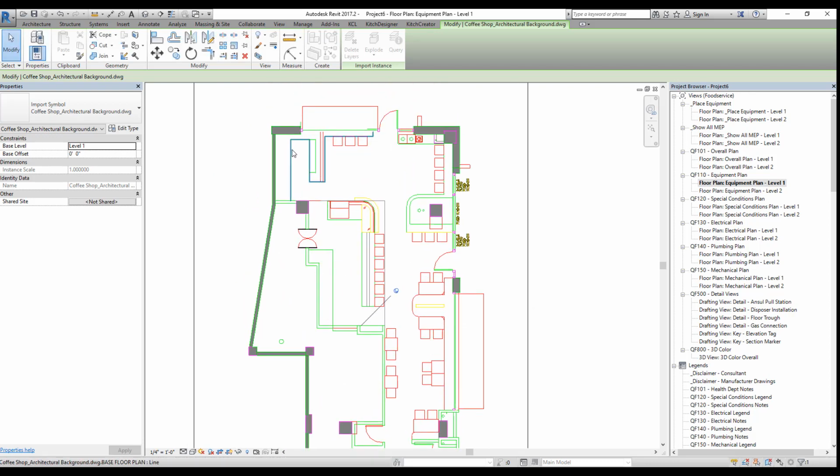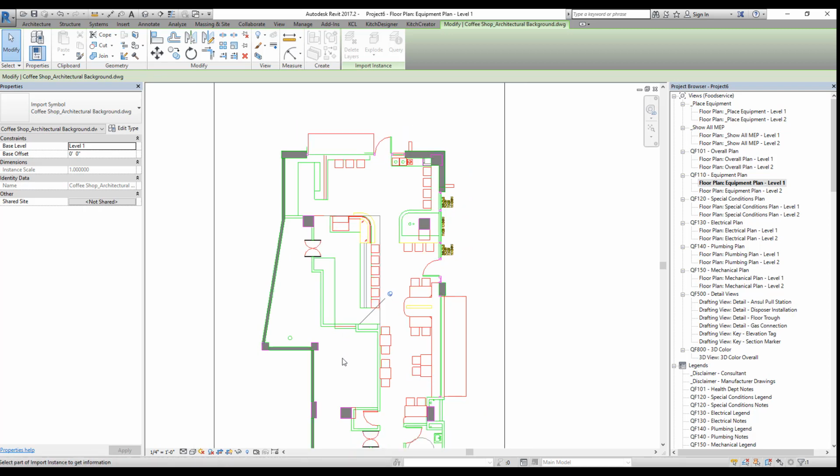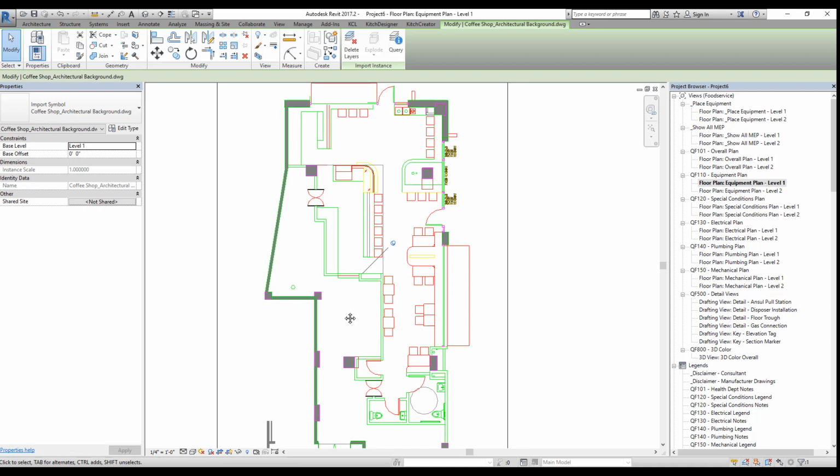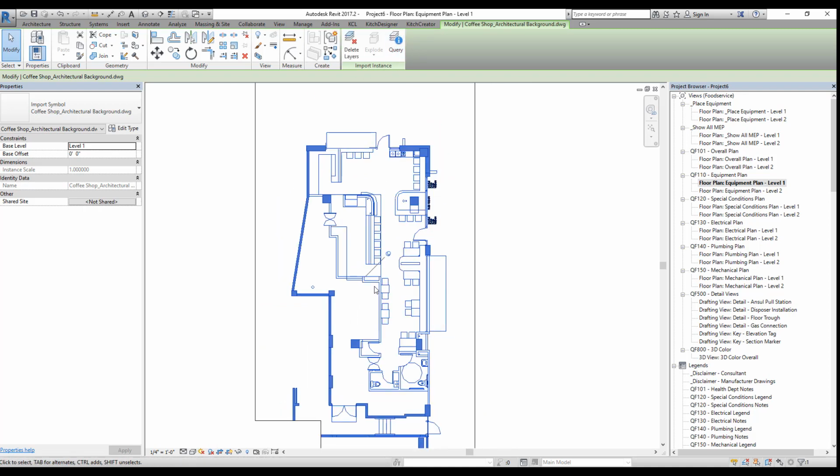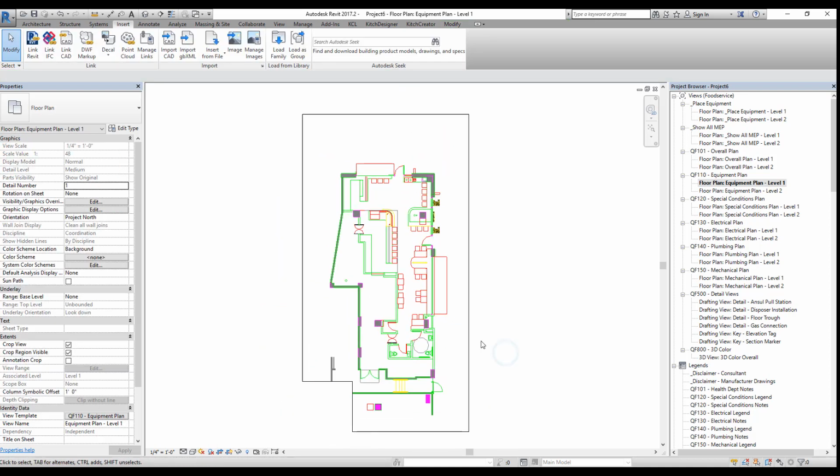And there we go. These are countertops. We're going to leave those as a bar. Here are our walls and our doorways. And this is some other dry wall, and looks like some more countertops here. So I'm going to press escape, which will close out of the query button, and just zoom out a bit. And that is how you clean up an architect's CAD file, background file, or DWG file, all the same thing, before you're ready to place your food service equipment.